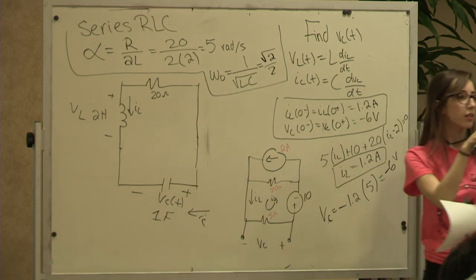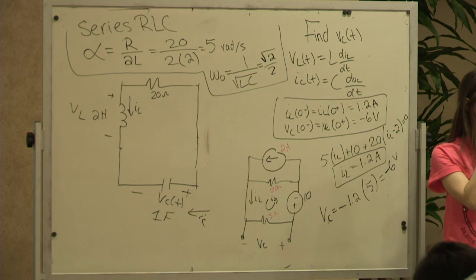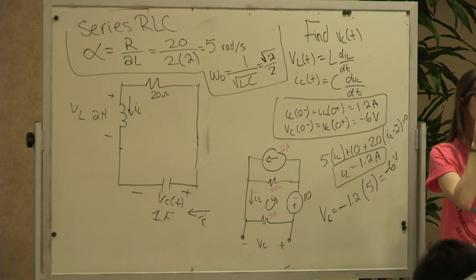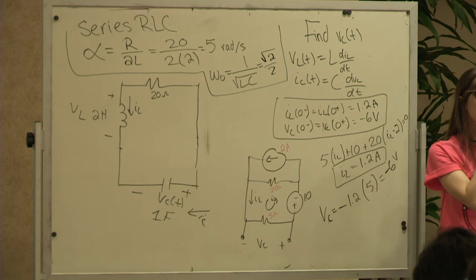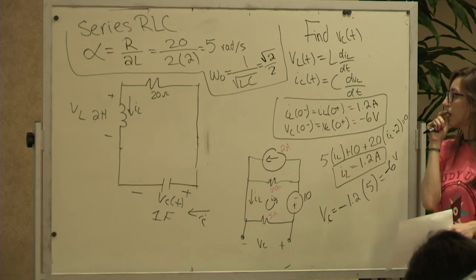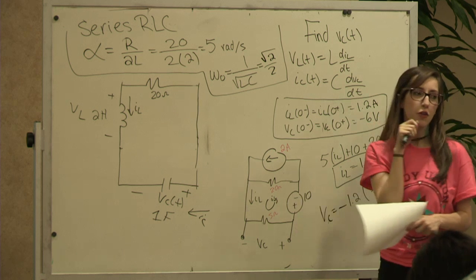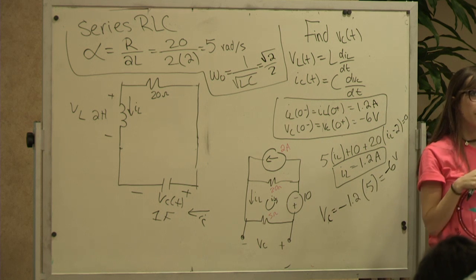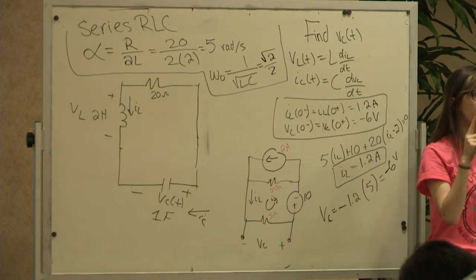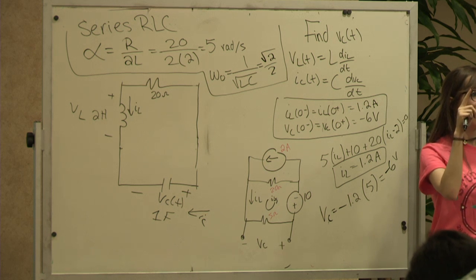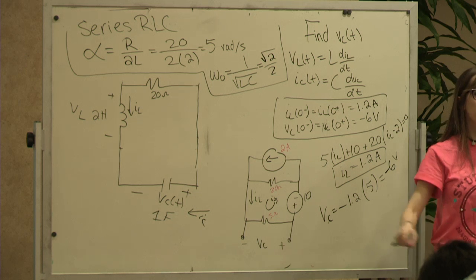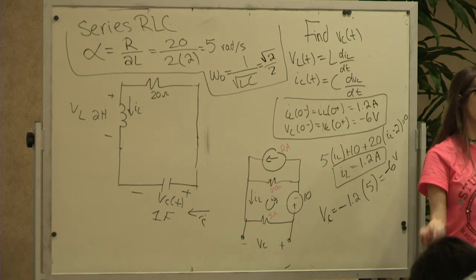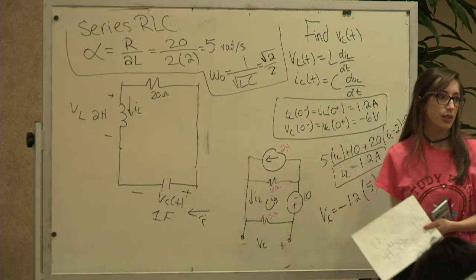Oh, hey. So you're saying that if we can't already tell, like when we first get it, if it's series or parallel, we can always use deactivation to tell? Yeah, just not with a dependent source. Normally, even if you do have a dependent source, you could probably do a super mesh or a super node. A super node would mean everything can be represented in one KCL, so it'd be parallel. Super mesh would be one KVL, which would be series, if you had a dependent source, because there are problems like that.